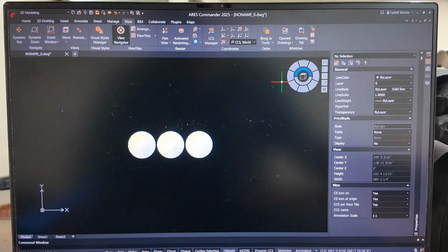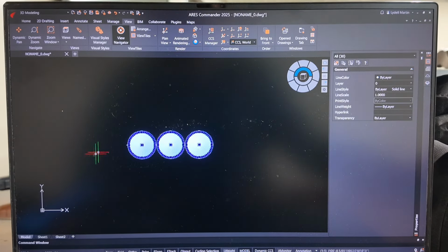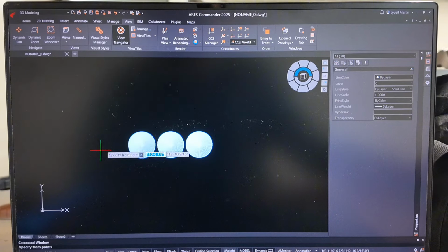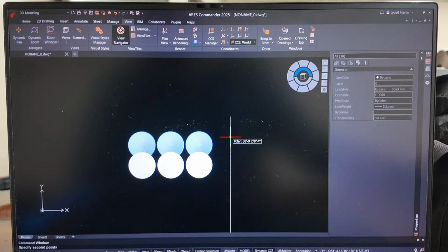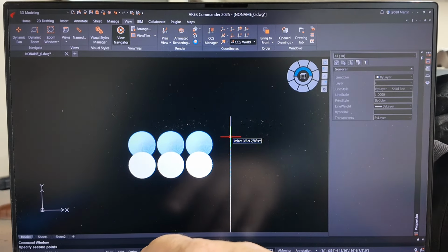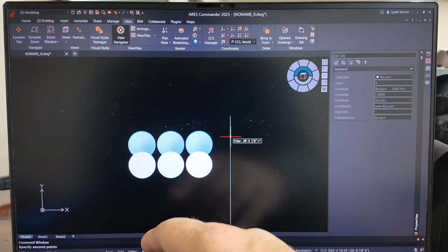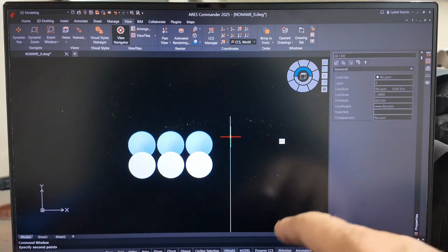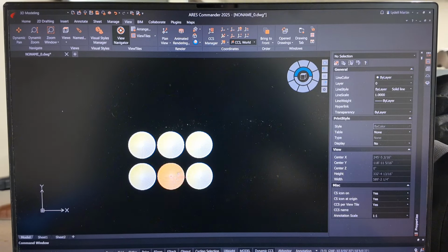And look, we are making a row of grain bins. And then if we decide, right click again, copy, and right here we left click, we move down, and we want to be the same there. So actually we want 12 foot between the bins in case we want to run a drag conveyor down through. So 48 plus 12 is 60 foot. So we type in 60 foot, enter, and it drops a row there.